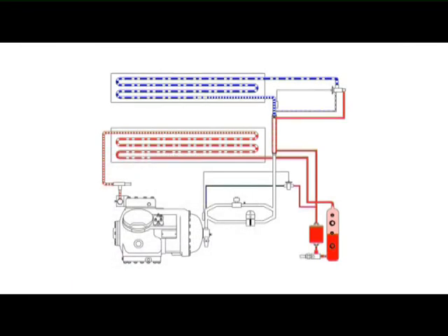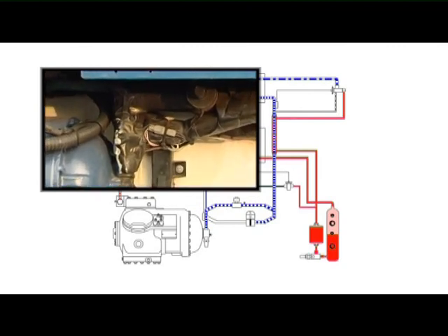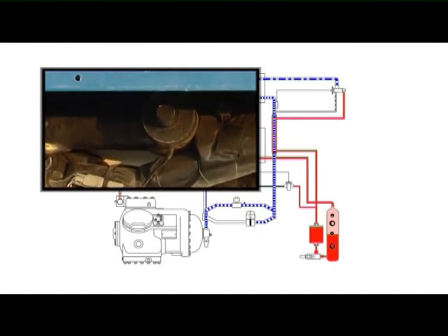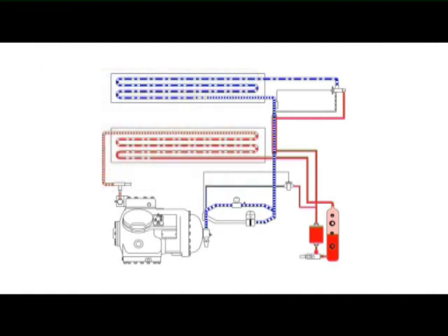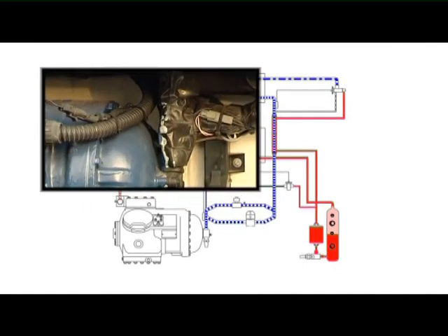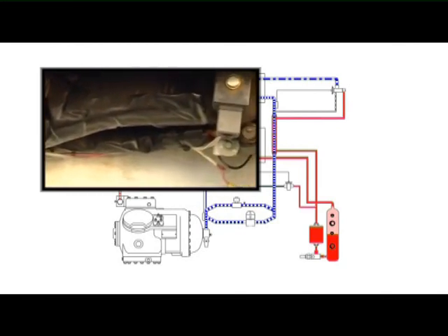The low pressure and the low temperature superheated vapor in the suction line passes through the heat exchanger and flows to the suction modulation valve. This valve is a valve with an infinite opening to ensure the system reaches the desired box temperature. For frozen cargo, when more capacity is required, the suction solenoid valve will open as well.